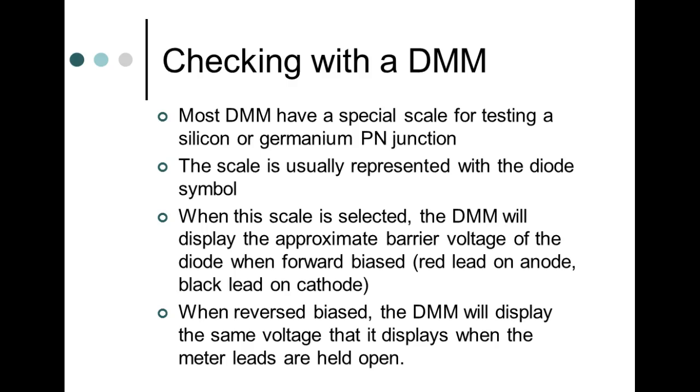And they have a VF that's pretty high, usually around 2 volts. So usually our meters will not break that over. So you cannot check an LED with this meter. The only way you can really check an LED is to put a battery in series with it or put it in a circuit. Of course, if it's working in a circuit, it's pretty obvious because it's going to do what? It's going to light up.